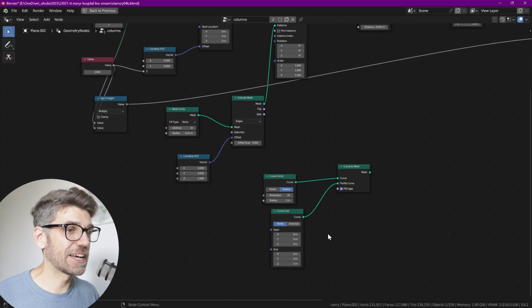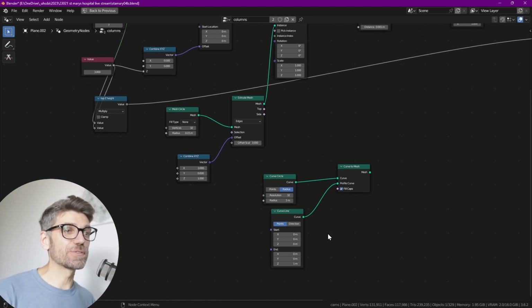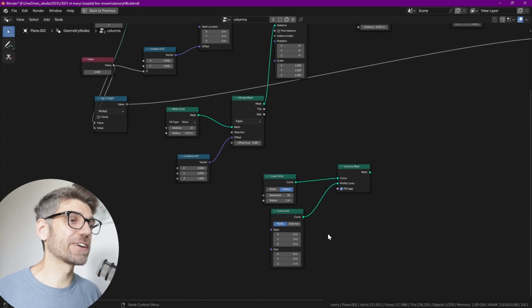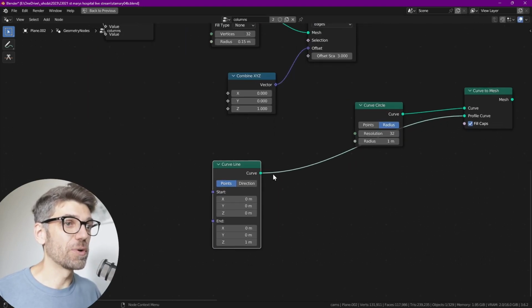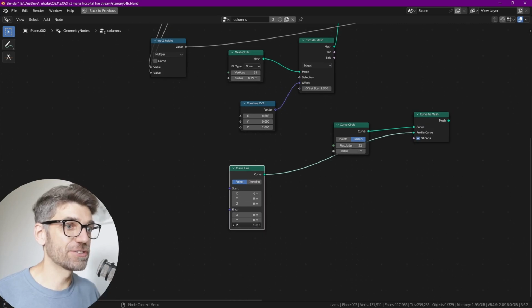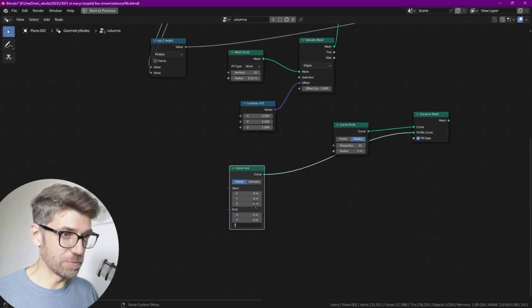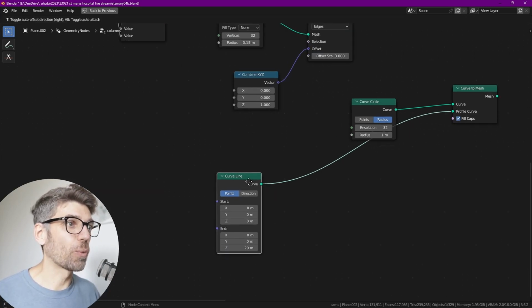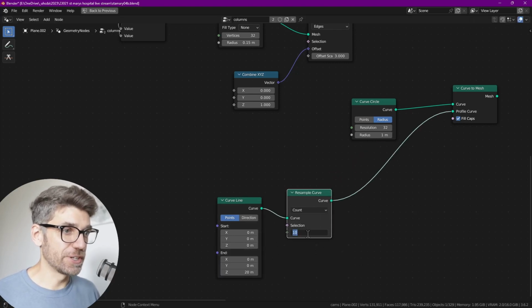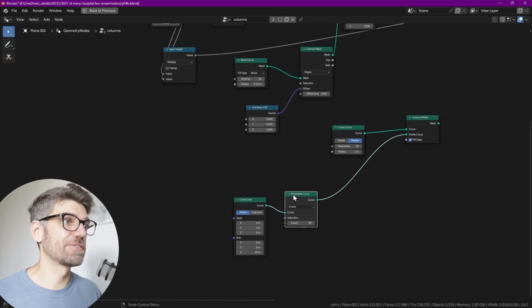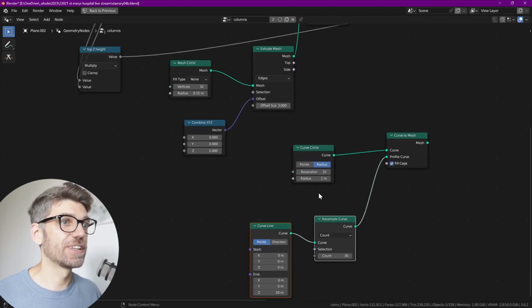However, I'm just thinking now, it's still not giving us the right way, because we're not going to have a curved top and a curved end, even if we do a small section. We can though change, yes, that's what we can do. We can change the dimension of this curve here. So we'll make it the overall height first. Because we're aware that we're going to have setbacks, something like 20 meters, and then we can go in there and say resample curve and change the number to something like 30. So now that curve has been subdivided a bunch of different ways.